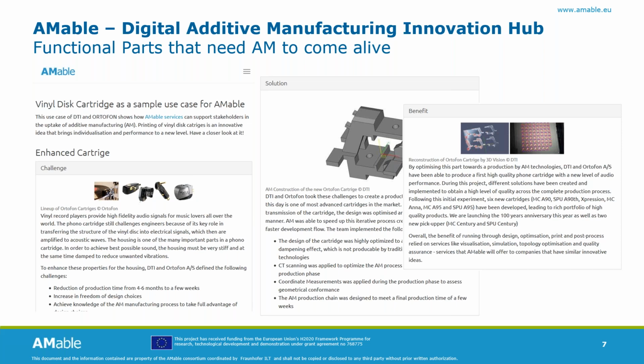This nicely shows that if you can integrate a larger number of subcomponents into one part, then you have an advantage because you don't have to do the assembly, you don't have to match tolerances of those assembled parts and so on. And this one here really provides you a better sound performance because you can calculate how the vibrations are being transferred.